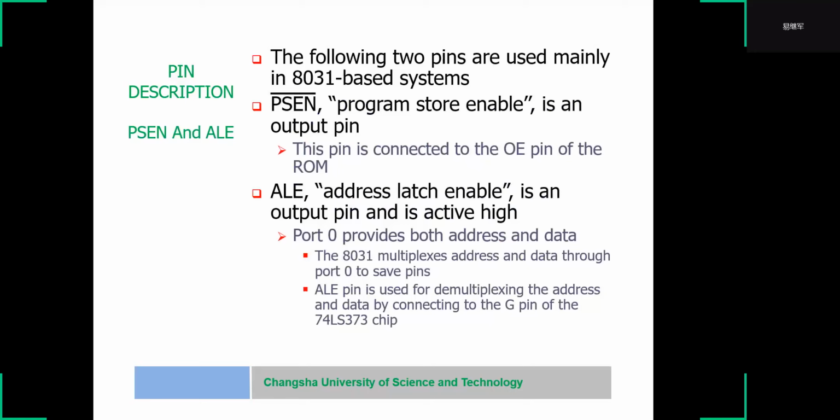The following 2 pins are used mainly in 8031 based systems, but also used in 8051. PSEN, program store enable, is an output pin.